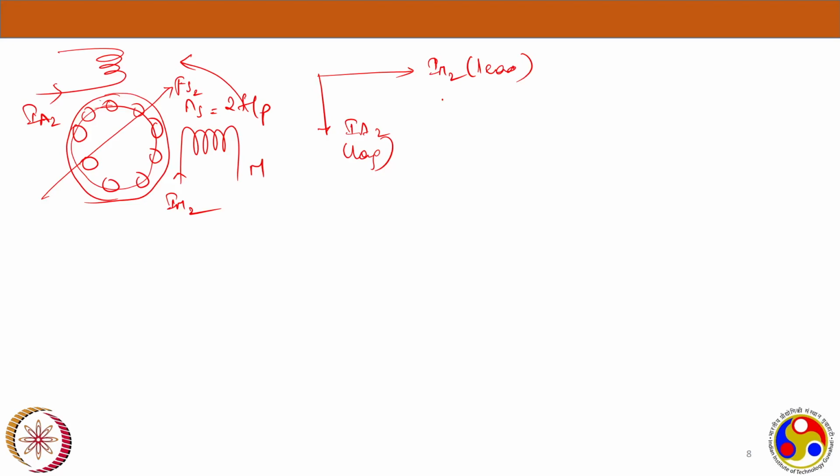The reason we have introduced this auxiliary winding and are doing it in the sequence cases, positive sequence and negative sequence, is because then they will be balanced and we will know the RMF directions and all. Now you add up these two conditions, case 1 which is positive sequence, case 2 which is negative sequence. If you add these two, it gives us the case of a single phase induction machine, where there is only one winding, the main winding, and the auxiliary winding effect will not be seen there. That we will see in detail now.